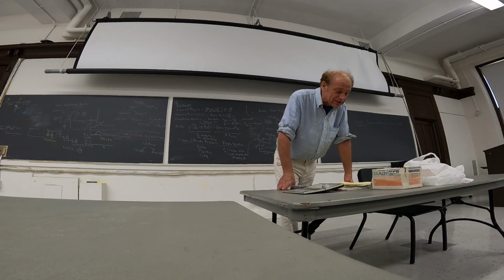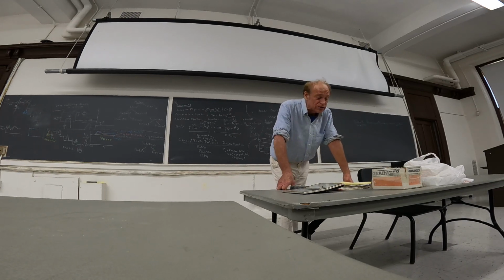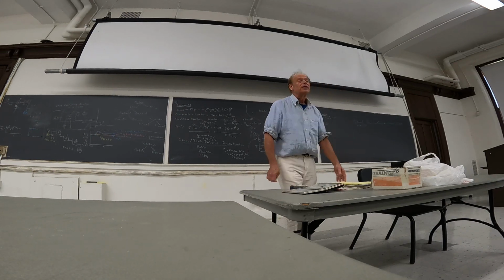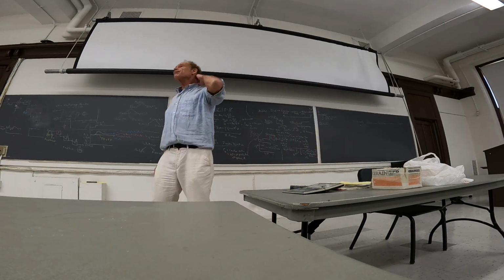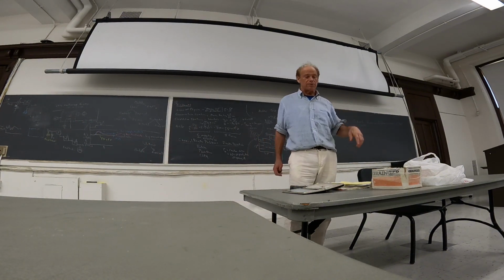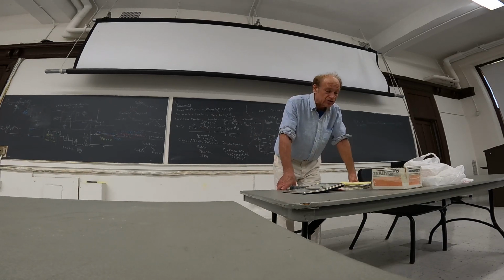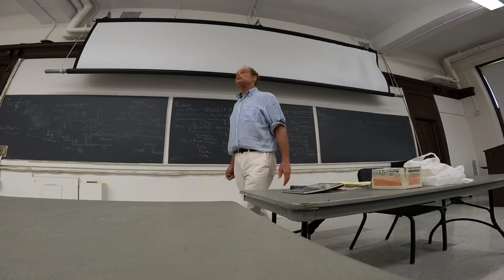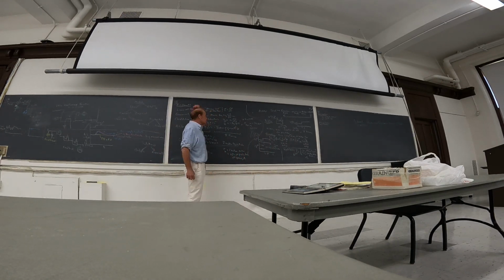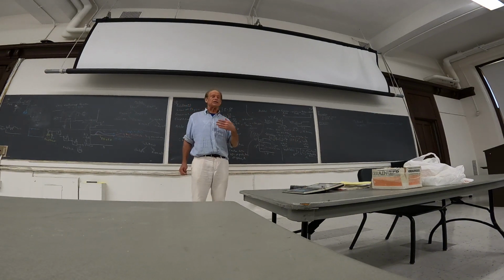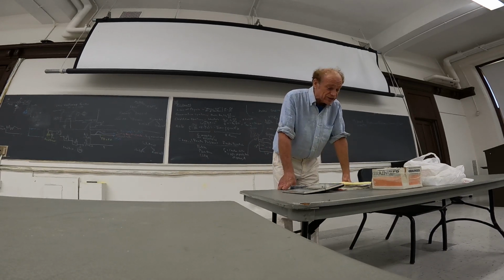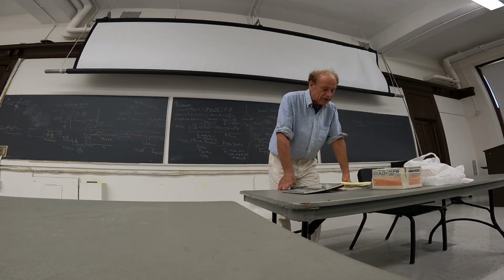And let's now look at which equations we need. Okay, so how do I know what equations to use? Here I'm speaking more generally rather than for this particular problem. If I'm trying to calculate a total amount of mass or a pressure, then what I would use is the conservation of mass. The conservation of mass is a method for figuring out the total mass, how that changes, if that changes, by stuff entering and leaving.